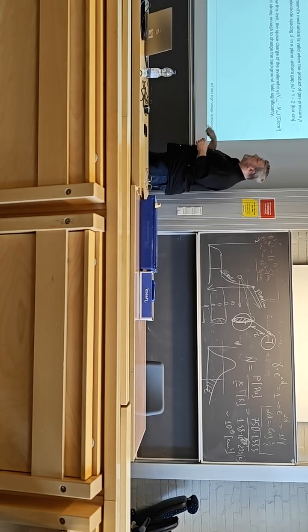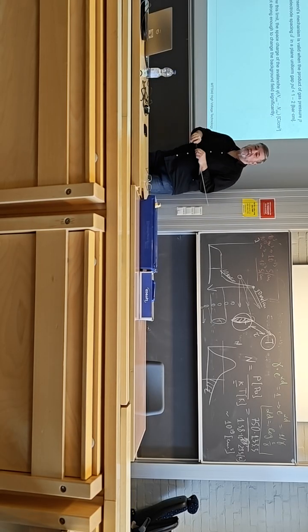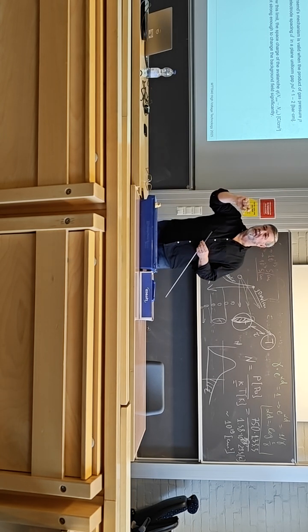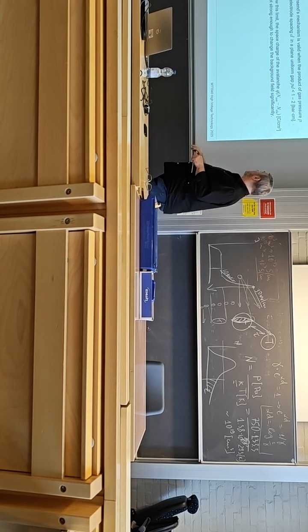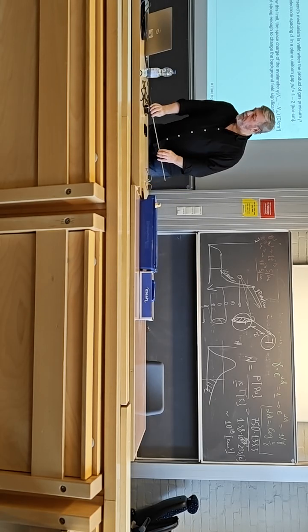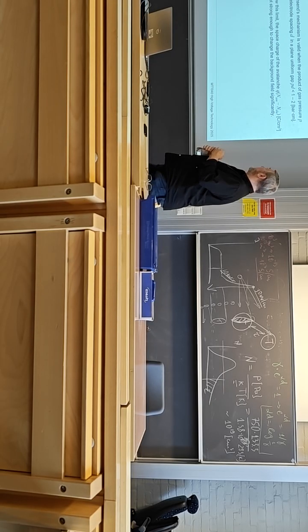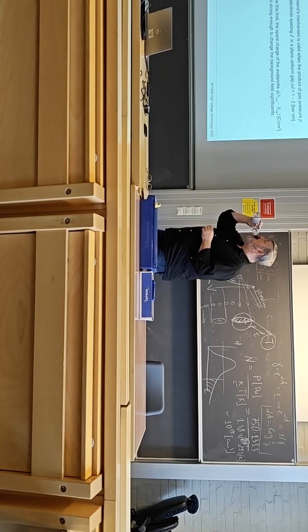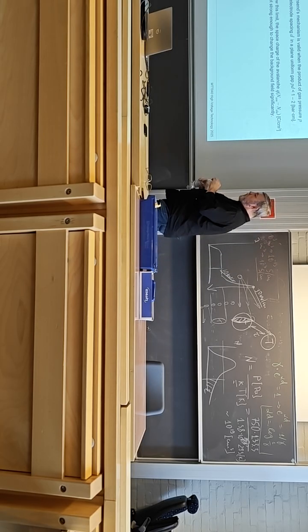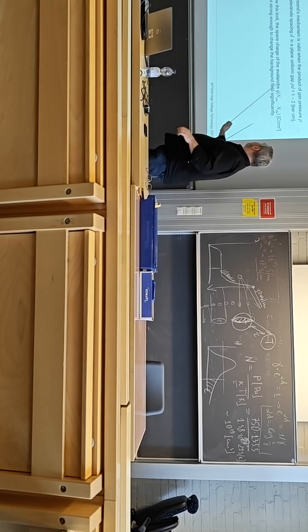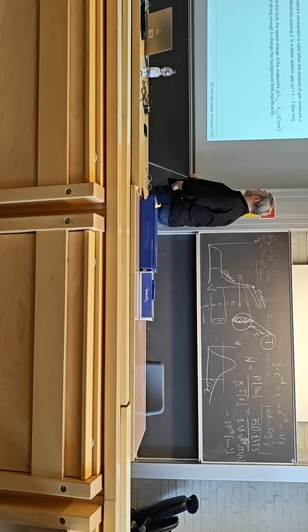If pressure is 1 bar, the Townsend mechanism is usually valid in gaps which are shorter than 1 centimeter. Or if you go to reduced pressure, you can consider larger distances. It's a product, p and d. That's what is called the similarity factor. What happens at higher values, we will consider later.